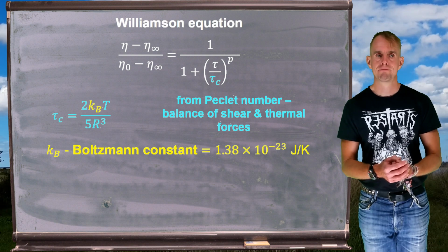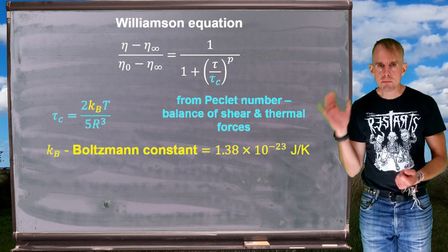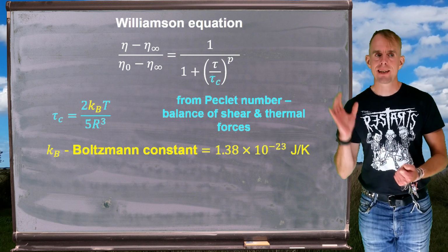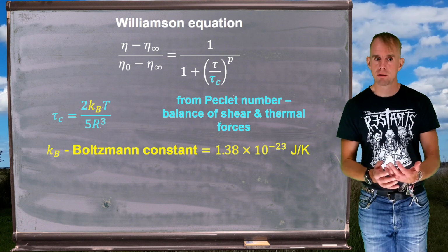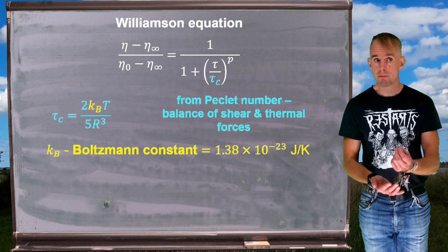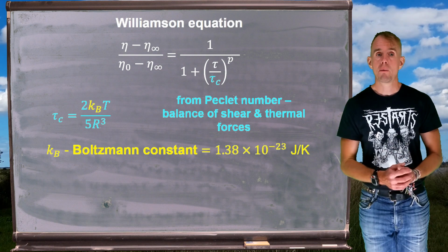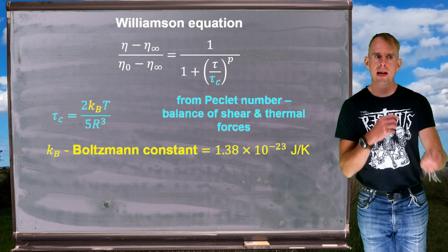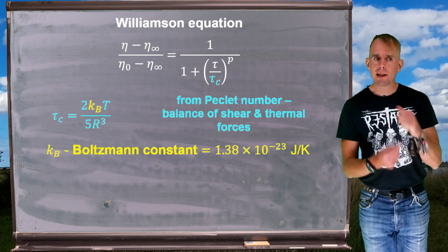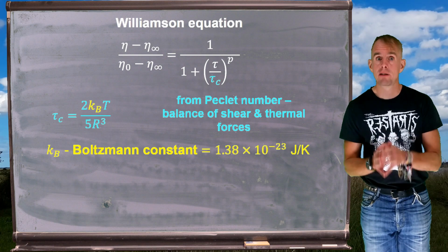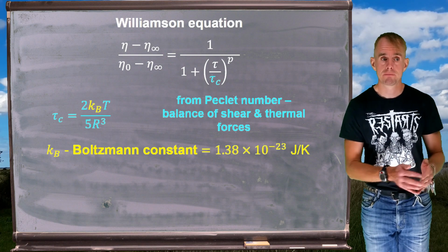we've been discussing. If we examine the expression for critical stress a little more closely, we can see that there's that term k_B in the numerator, the Boltzmann constant. Key thing about the Boltzmann constant, it's a very small number. And in the denominator, we have an r cubed term. So if we imagine that ratio k_B over r cubed, if that's to be order 1, r has to be very small, hence the applicability only to colloidal systems.